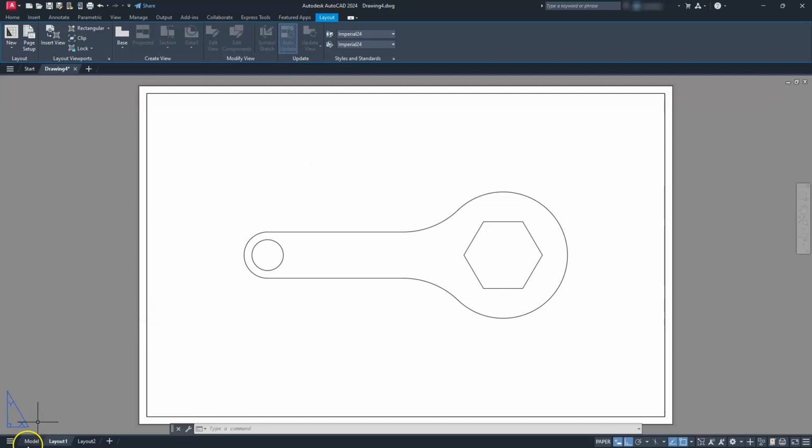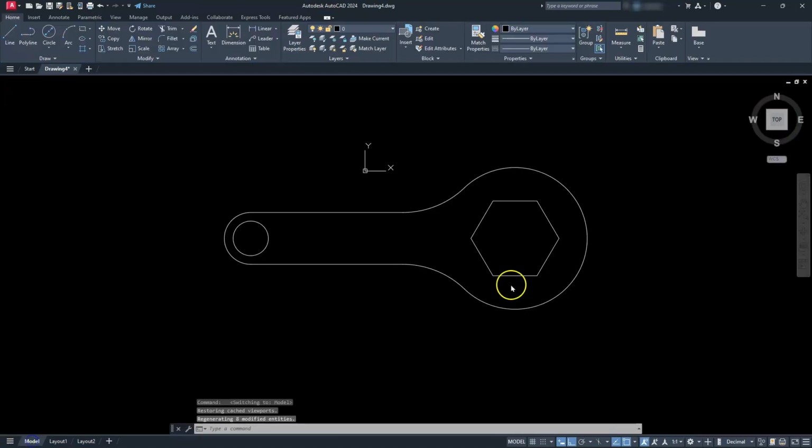Let's jump back to the modeling tab here real quick. And then I'm going to go ahead and put on the center marks, right? Before I do that, I'm going to go ahead and adjust the extension lines on my center. So center EXE. Go ahead and hit enter. And like with metric drawings, I usually like to set that number to either 3 or 5. I'll kind of leave that up to you. Let's do 5 for this one.